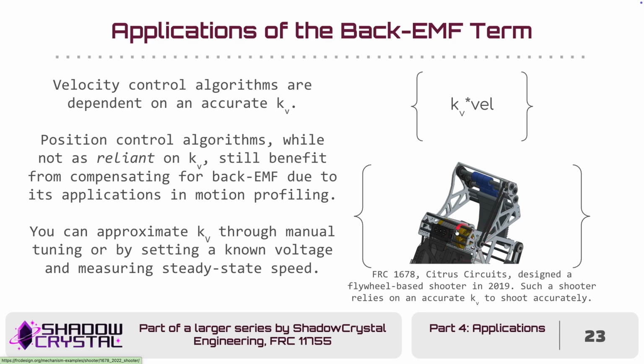If you can't tell, this is a little flywheel drum right here that gets up to speed to fire projectiles out this way. And in order to hold the speed well, you need this steady-state feed-forward term in order to consistently counteract back EMF in a way that your feedback controller can't, because your feedback controller is dedicated to keeping error at a minimum, not holding a certain state.